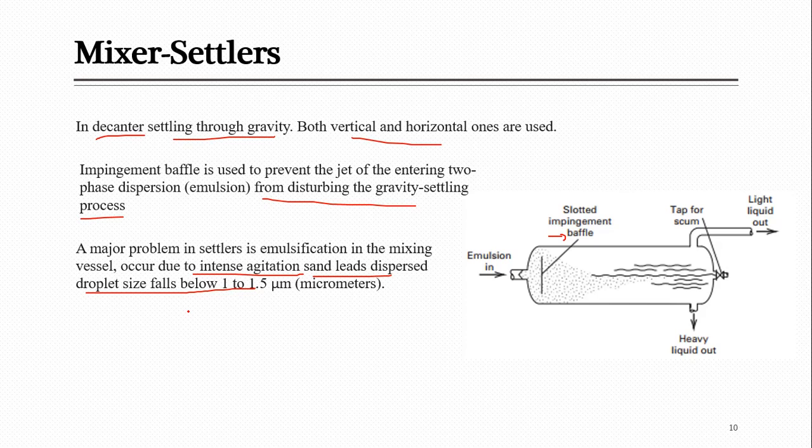If emulsion is taking place, definitely this gravity based settling is not going to help us, so we have to look for some alternative option, like centrifugal or maybe other. In the case which we have just discussed, if strong emulsion is taking place, then not gravity, but external force or treatment will be needed to separate them.